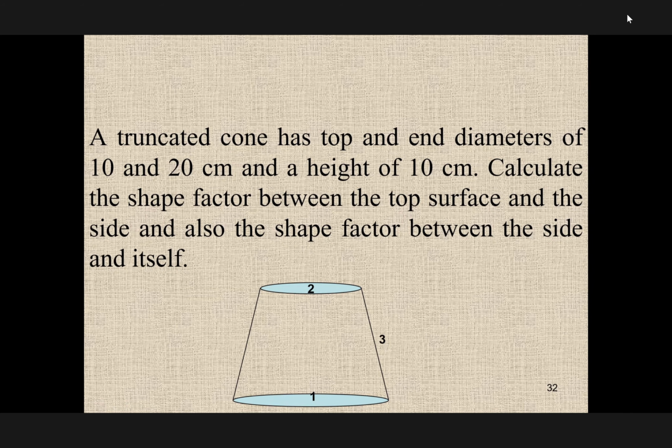But what we can know is 1 to 3, by doing 1 to 2 plus 1 to 3 equals 1. So write it down. Okay. Summation rule mentioned F3 to 1 plus F3 to 2 plus F3 to 3 is equal to 1. I do not know F3 to 1. There's no way to calculate because I don't have the graph for it. F3 to 2, I cannot calculate because there's no graph. Therefore the 3 of them are unknown.